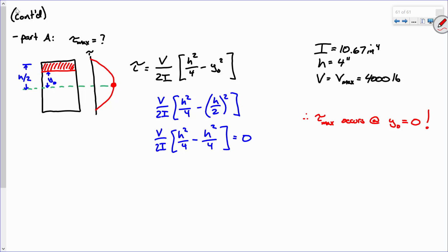Yes, sir? So the graph, that's like the Z shape, that's just regular stress. Yeah, that's bending stress. This is shear stress. That's a really good point to make. When we're talking about bending stress, the worst case bending stress is either on the way, way, way tippy top of the section or the way bottom. Worst case shear stress for this rectangular section is in the middle. Make sense? Not too bad, right?